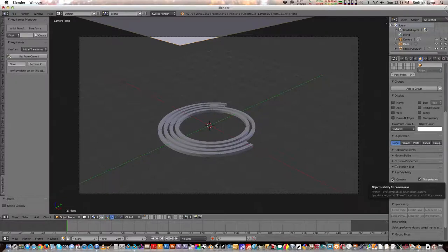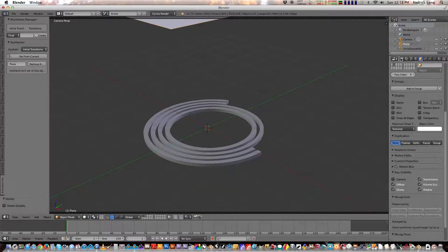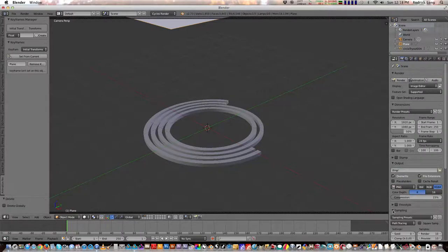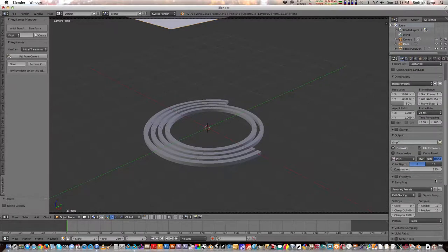We'll still get the benefits of the rays of light, but you won't see the actual plane that creates the light. So I'll go in here. Blender does everything in samples, so you kind of want to have a high sample. I'll just do it to 25. Well, that's the render, but the preview sample is what we want to be concerned about now. And actually, I'll do it to 100. I'll basically pause the video and skip ahead so you guys can see it, but